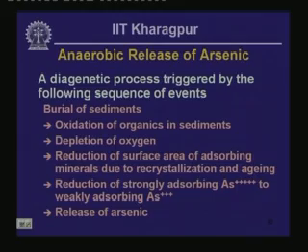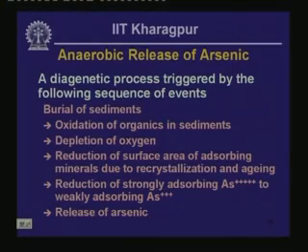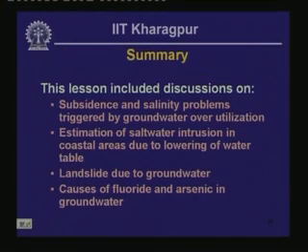And because the lower reaches of the Ganges-Brahmaputra delta are also affected by very low hydraulic gradient, or very slow groundwater movement, the arsenic that is released remains or accumulates within the groundwater. So the problem doesn't go away very fast, and it remains a problem over a relatively long duration.